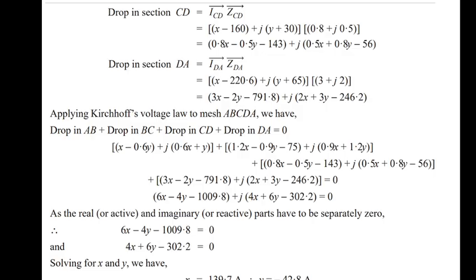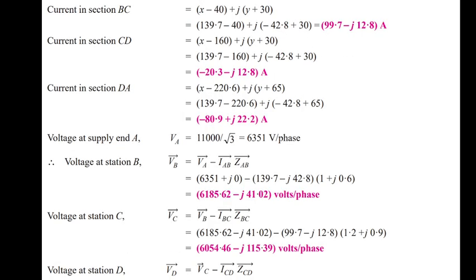So by solving these two equations, the values of the currents can be determined, and given the current in sections A and B as a complex phasor. This step is crucial as it finalizes the current distribution in the entire ring network. All right. In this slide, we finalize the analysis by calculating the currents in all sections of the ring distributor